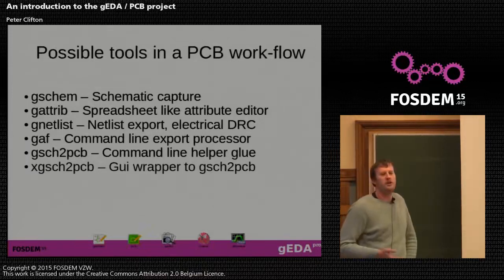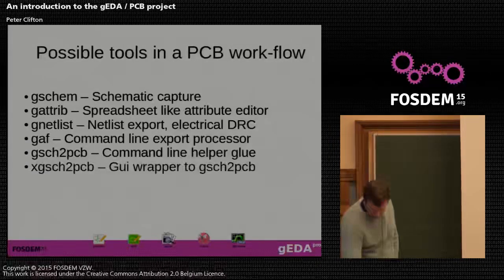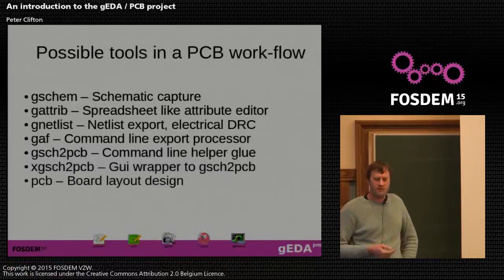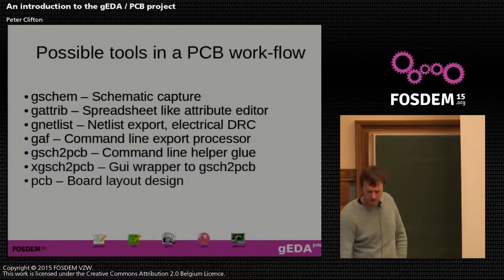And we've got, of course, a board layout package now. That's a different code base, and we'll move on to that shortly. GerbV, GerbViewer. Obviously at the end of your PCB layout escapade, you probably want to actually produce a circuit board, and to do that you need manufacturing data. But you'd be foolhardy to do that without at least checking the manufacturing data looks correct, especially with some of our code branches.